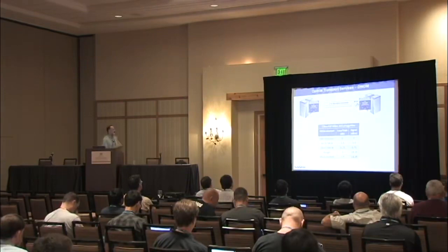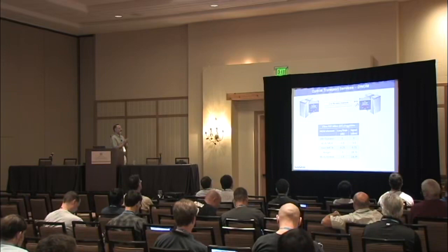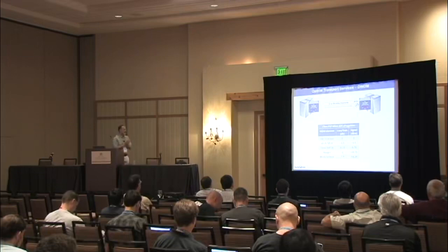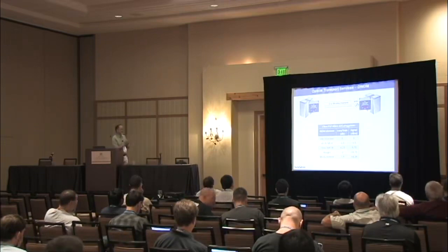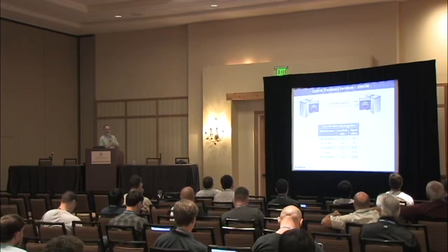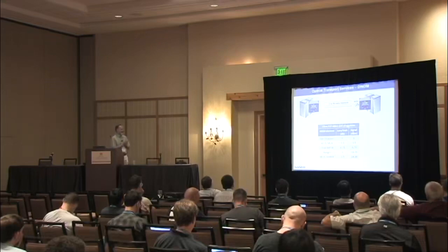Now let's look at a simple example of doing WDM, 25 kilometer point-to-point, using 40 kilometer 10 gig optics. We are starting with 10 gig optics at 0 dBm. The 40 channel Mux adds an attenuation of 3.5 dB, bringing the signal to minus 3.5.